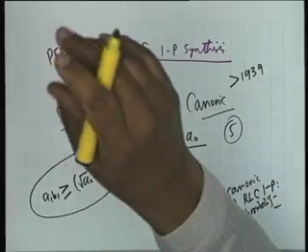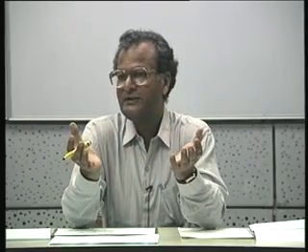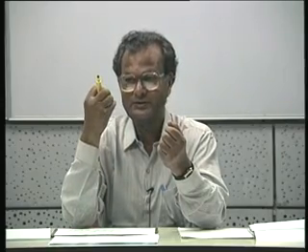See, a transformer is not a very favored element. A transformer has a lot of problems: shielding, core, it becomes heavy, it becomes bulky, it picks up things, magnetic induction and things like that. Where you cannot do without a transformer, you have to, in power lines for example, transmission, distribution, then in matching for audio frequencies and so on.